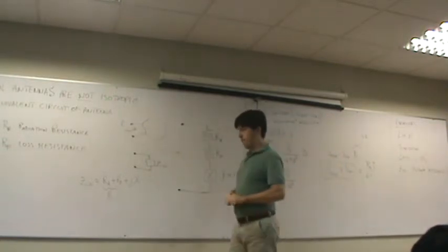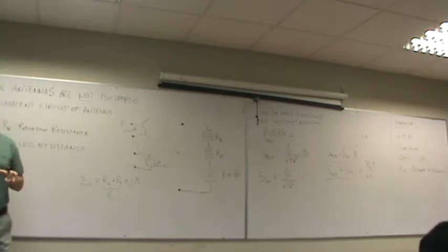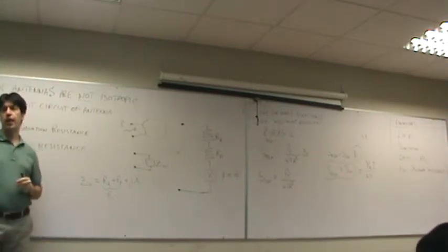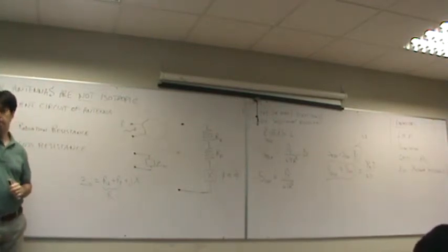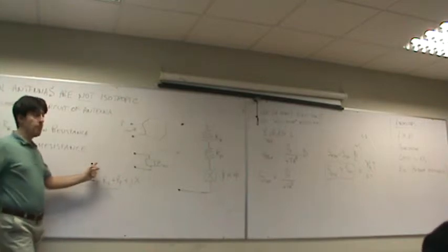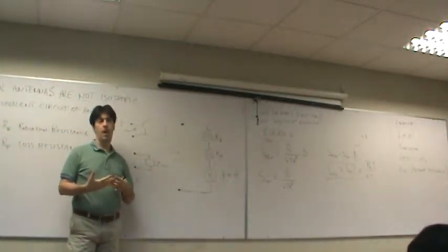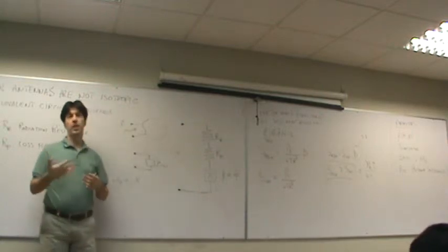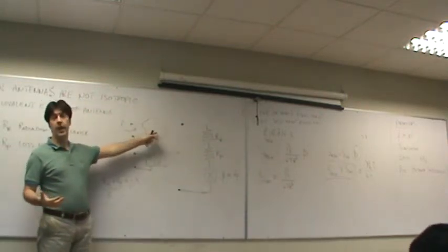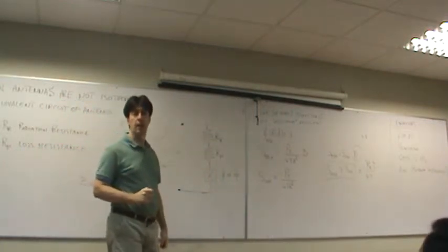And why is it important? Because you have to connect the antenna to a transmission line or to a generator. It is extremely important that the impedances are matched. In our practical world, this means that the impedance of the antenna must be the same as the impedance of the transmission line.